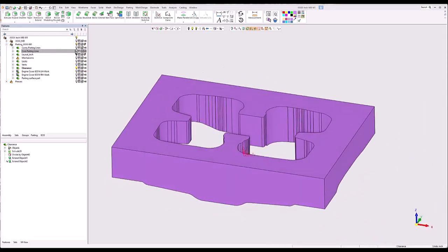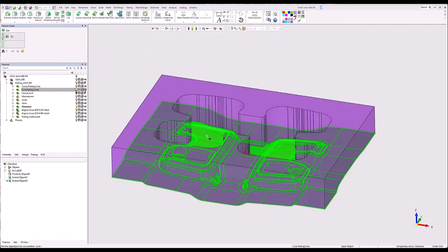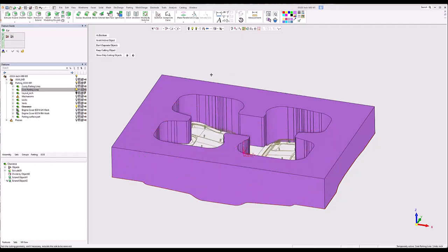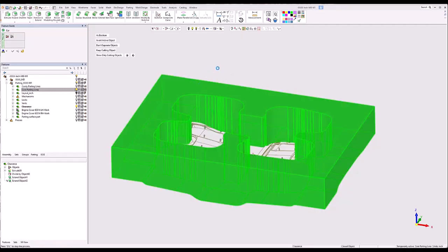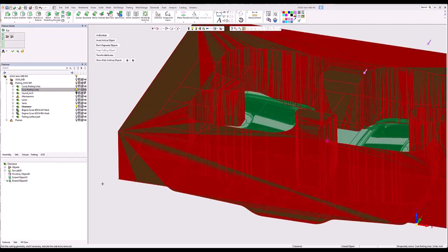Okay, we're going to cut the clearance into the core skin. So I can pick that, pick this. Now when you're dealing with a skin, inside and outside is a little bit ambiguous. One side has to be inside, one side's got to be outside. And it's being able to recognize before I say OK. Otherwise I have to do an edit feature and do this next step.